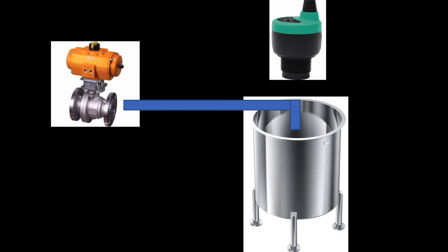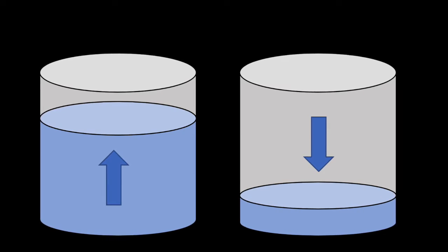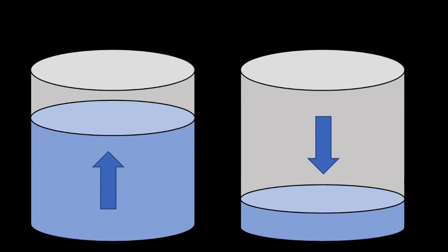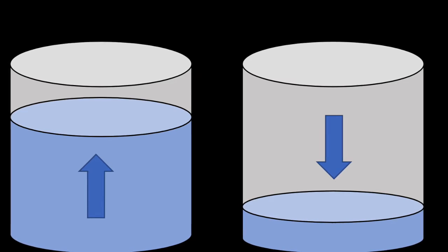Our goal with this project was to fill a tank with 100 gallons at a max flow rate of 4 gallons per minute. We didn't want any overshoot because this is based on a chemical recipe, and we didn't want to add too much water and influence the quality of the solution that we're creating. We wanted the system to remain inactive while we were mixing the water with powder and also while the tank was emptying, and we wanted it to begin filling when it was completely empty.